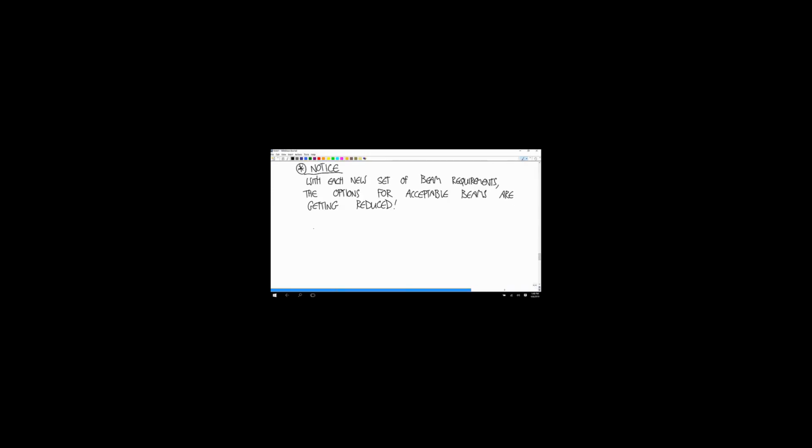So before we can, the formula for the stress due to shear force is tau xy, the shear stress in the xy spot, equal to negative V times Q over I sub B. Again, the sign will work itself out for you.